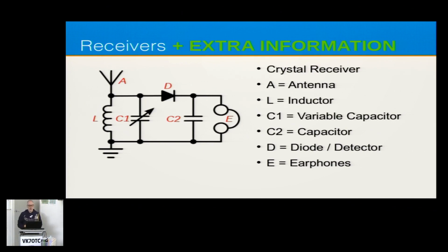Now that's our detector, if you like. That's the thing that rectifies or converts the radio signal and pulls out the audio signal for us, so we only get the audio signal out the other side. That's really handy because we get rid of all that RF. This bit enables us to tune up the RF and tune to the station, whereas the diode then pulls off the audio.